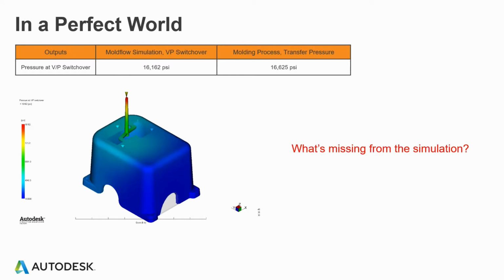Yeah, one thing I'll mention, when I did this full time, we would actually model up the standard set of nozzles that we had available for all of our molding machines so that the analysts could include those per our specification in the analysis. And so we had a good idea of what that would be in the prediction. So that is one option. You just have to know what your available nozzle is. In our case, we standardized those and blueprinted them and then provided the designs.